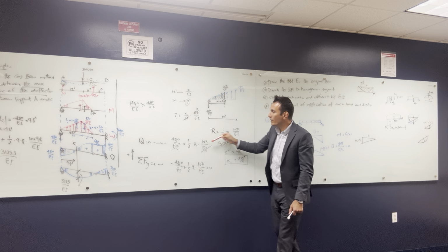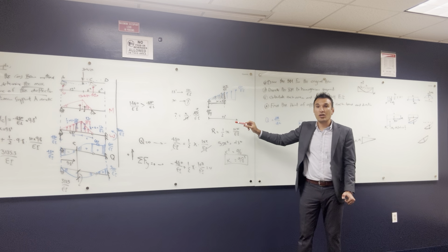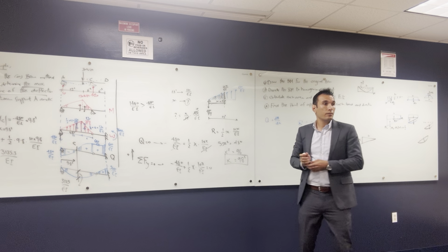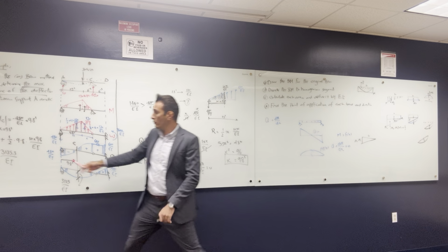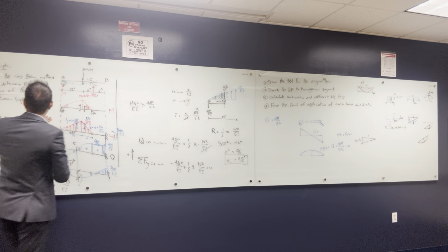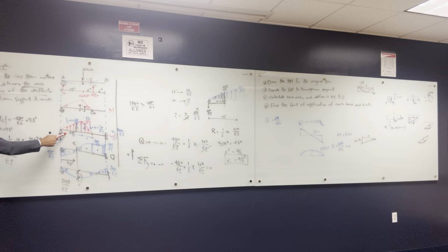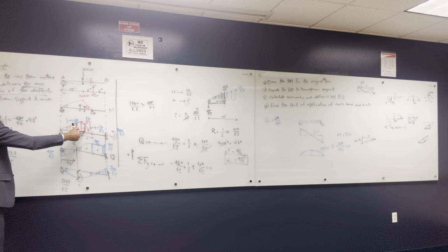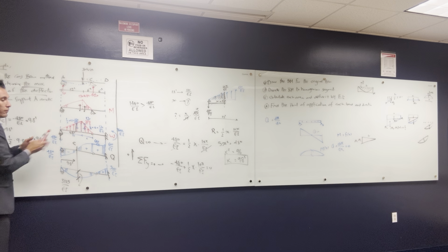What we did here, you should have done in the basic structural analysis class. Question: that moment that you did, was it just from the shear diagram? Yes. The moment that I got, I used the reactions and the loads to get the moment. When I derive any moment, I always look at the original beam, or in this case the conjugate beam. Even drawing the shear, I have to look at this load to draw the shear, and I have to look at this load to draw the moment. Same way here: from W, I get shear. From W, I get the moment.